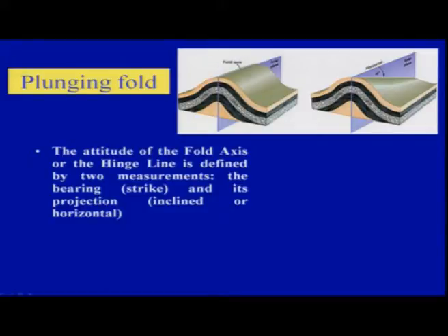Okay, and this is extremely important because we need to know where to put a tunnel. If you are planning to put a tunnel here, then the tunnel will go through and through across this bed. But if you are coming across the plunging fold, then your tunnel will last up to this only, where here you can go across this one. So that is very important in civil engineering, also for us in geology or the earth sciences. It is extremely important because we need to understand the evolution of the folds.